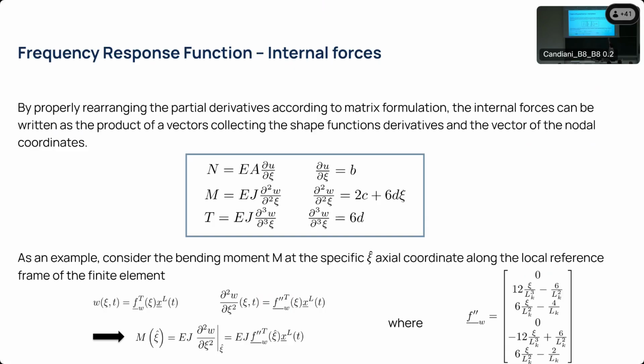Those terms are computed, while the terms we multiply them by, the values of the nodal displacement in local coordinates, are just what we extracted from the initial matrix. In case we have a rotated element or any change of coordinate system, we have to use rotation matrices, but in this case we are just on a line, so we can directly use the global coordinates.